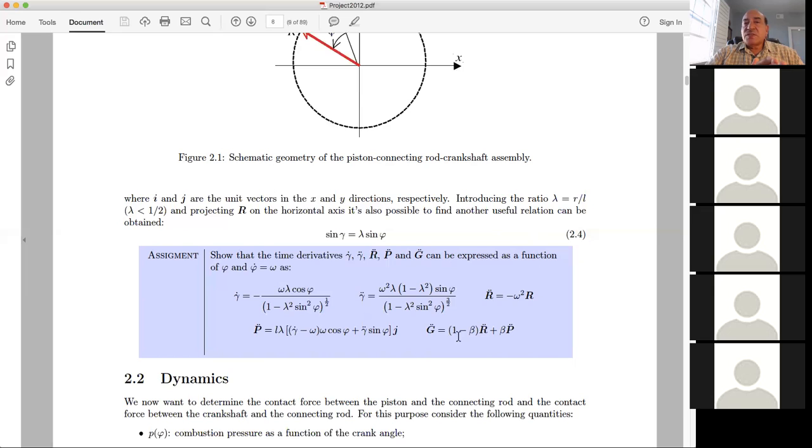So at this point, you have two choices. One choice is that if you find a pressure profile for your engine, you can digitize it and use it the same way, replacing that MATLAB list. It's like two columns. Or you can just directly use the pressure profile that is supplied in the manual.